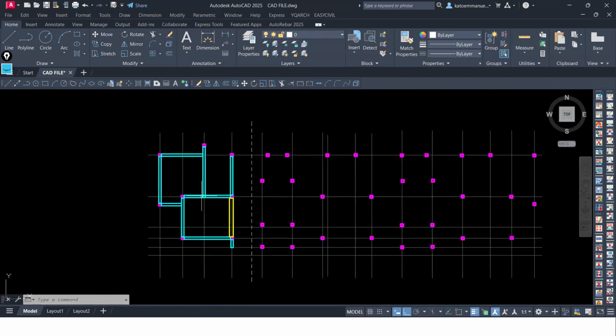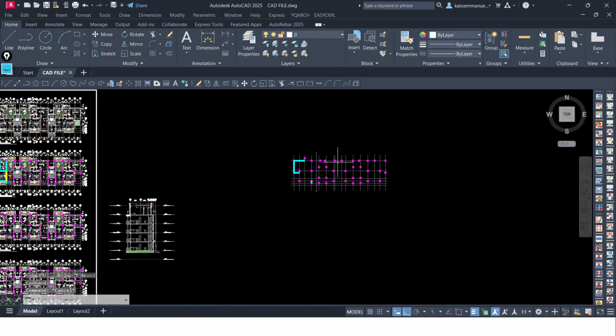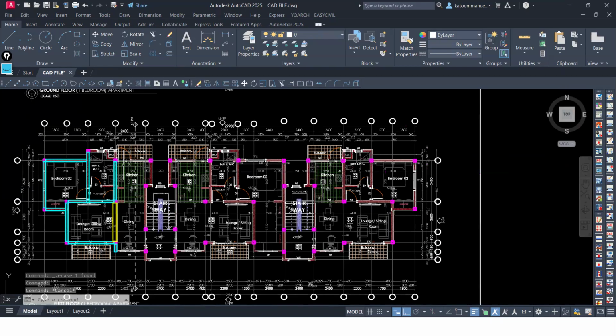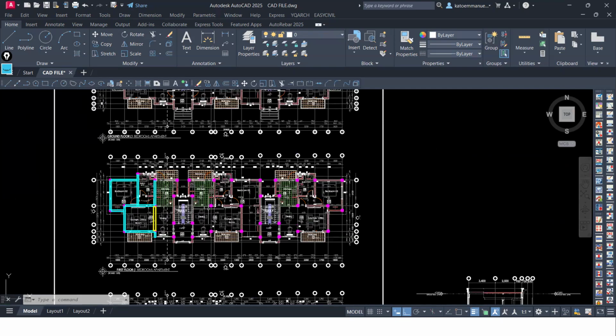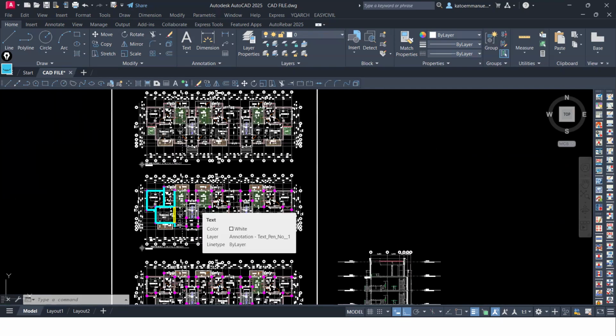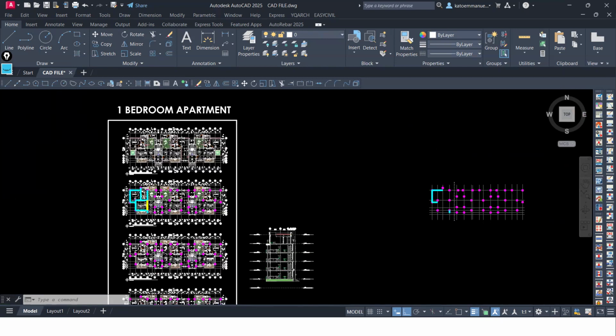So now, remember I said we do not need these beams for what we are going to take into Prokon structure. The beams we will recreate them, but we shall be basing on this one, on which supports connect to which one. It is better that way. However, much you can also import them, but there are some abnormalities which come with that.